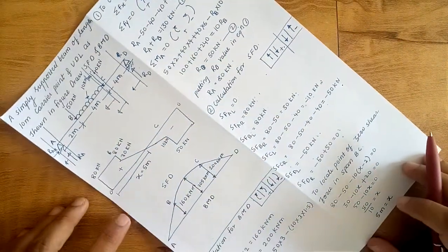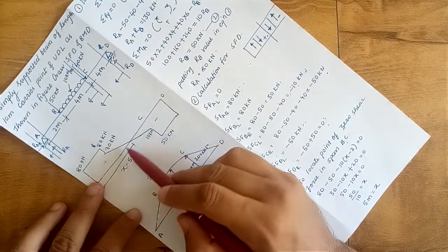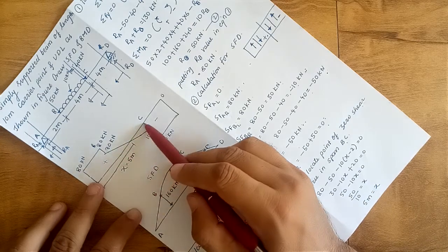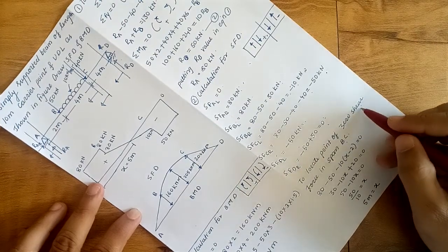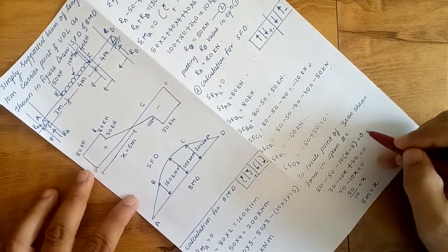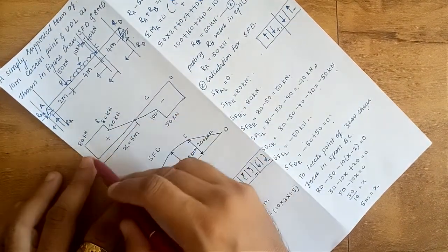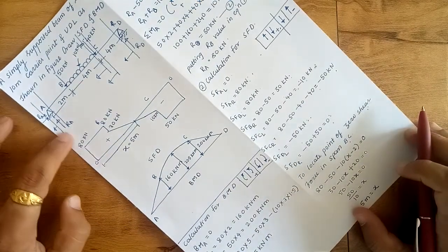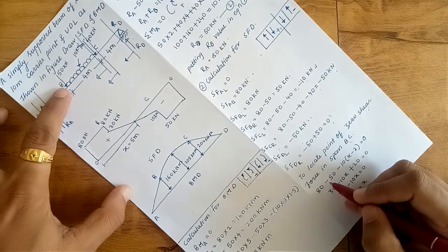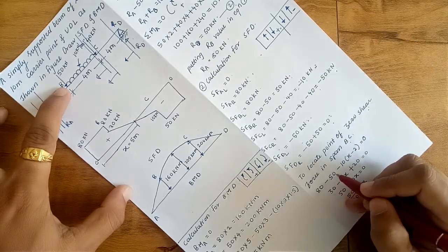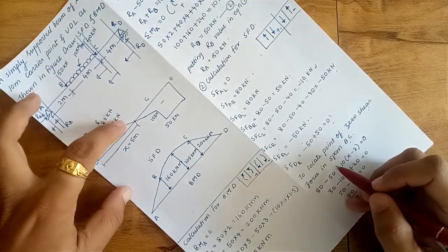So I have here given the explanation to locate the point of zero shear force in span BC. So along the span BC, this is the point of zero shear force. Okay, so for that I have given this equation. Up to this point I have considered all the forces in the left direction. So 80 kilonewton is in upward direction, so that's why I have taken 80. 50 kilonewton is in a downward direction, so that's why I have taken negative, 80 minus 50, and minus 10 kilonewton per meter load will be over this length.